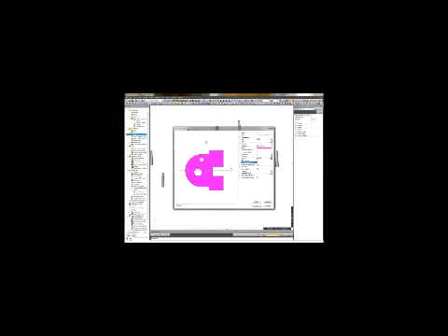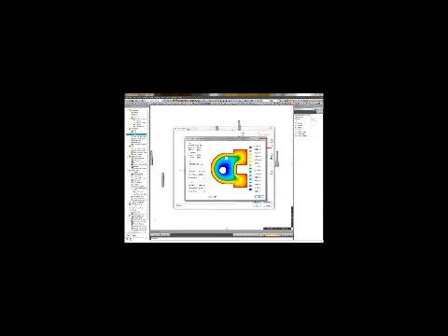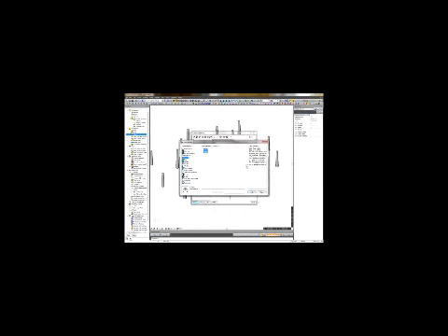For example, here we're assigning this cross-section finite element data, and we'll define the finite element mesh. With the mesh defined, you can see the FEM results. Here you can see the shear and torsional stress distributions on the profile, and we can even turn on the mesh. Once defined, we can add these new cross-sections to the program's cross-section library and then use them from project to project.